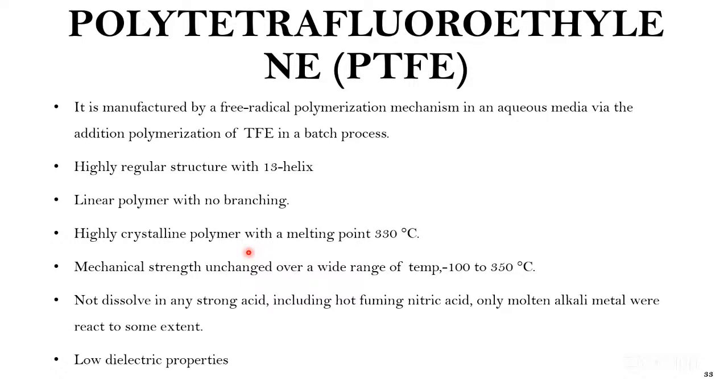If you have more amorphous percentage, only then can you see a proper glass transition temperature. Otherwise, if your material is highly crystalline in nature, it's quite difficult to find the glass transition temperature of that polymer.